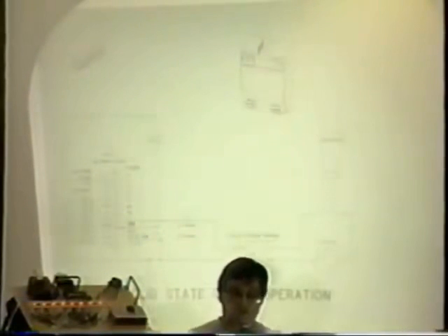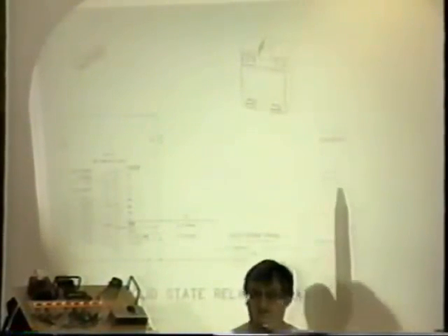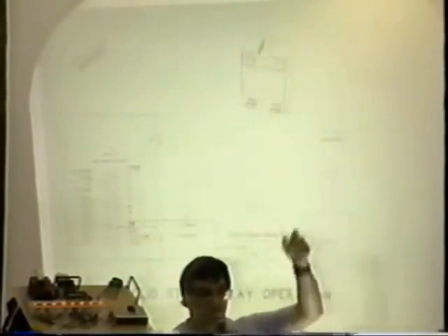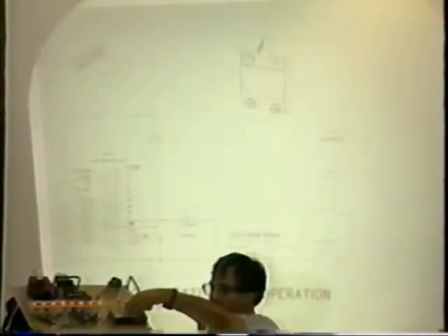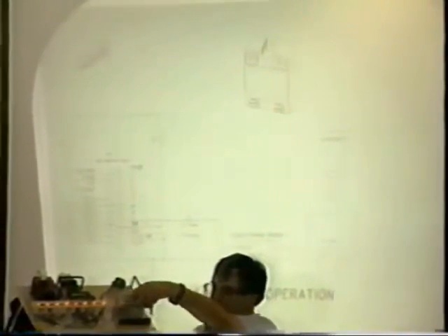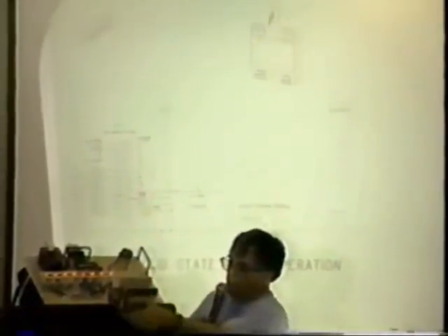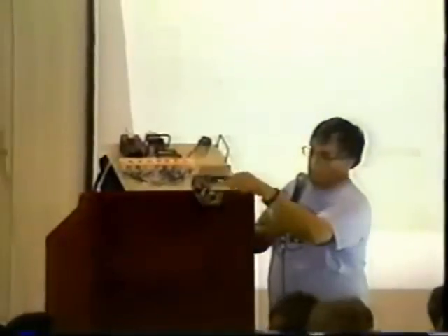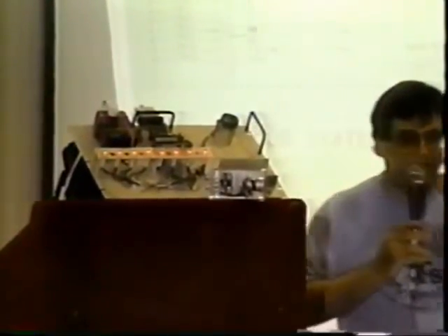The high power end plugs in the wall. So in fact, here's a solid state relay, and I'm operating 110 volts, a blender. Usually I'll bring a saber saw and I plug it in. Right here is a solid state relay, and the little black plastic thing with the 4 leads, that's the solid state relay. What's really neat about it, it already has a heat sink on it. It already has an LED, an optocoupler on it.